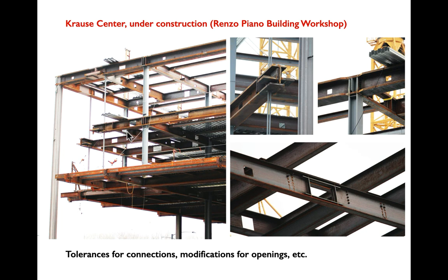Steel lends itself well to this kind of manipulation because it can be rolled in very thin sections. So these beams, these girders, all have sections that are less than ½ an inch thick, therefore easy to cut holes in it, easy to place those holes very carefully around the neutral axis where we know that they will do the least damage to the beam's carrying capacity, and therefore to integrate mechanical systems and structure into the same structural depth.